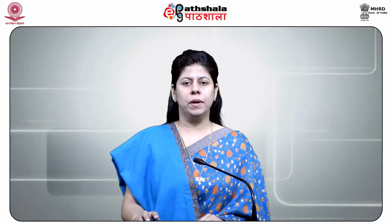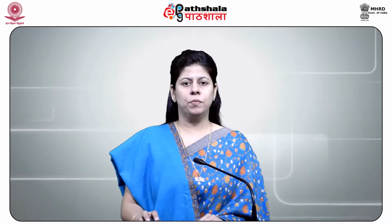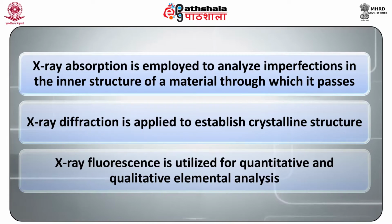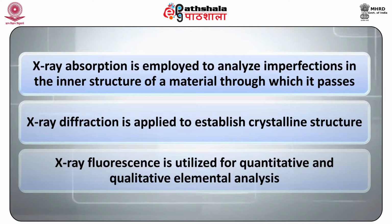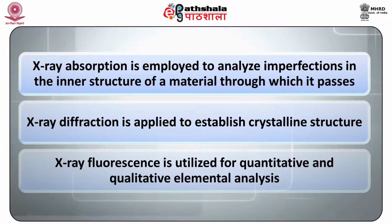Each of the mentioned methods is applied to different fields of analysis and depends upon different characteristics of the radiation. For example, X-ray absorption is employed to analyze imperfections in the inner structure of a material through which it passes. X-ray diffraction is applied to establish crystalline structure and X-ray fluorescence is utilized for quantitative and qualitative elemental analysis. All these three techniques are non-destructive.